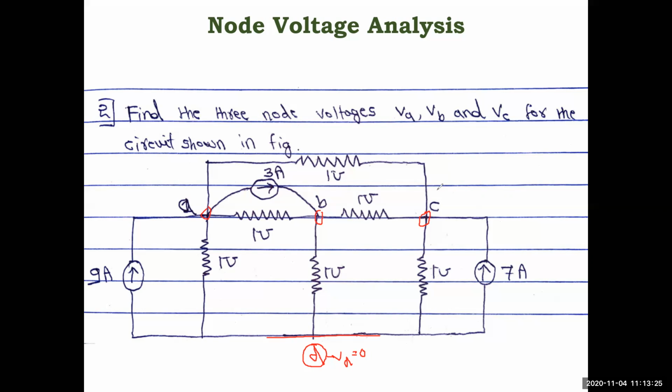Now what you have to do with this example: write three equations for node voltages VA, VB, VC. Use the calculator now. Earlier we have seen two unknowns, now again three unknowns. The a, b, c, d parameters of each equation you enter, and you will get VA, VB, VC. Simple one. The only confusion here is that they have given values in mho, so you should be careful. Now with respect to A, so what are the self